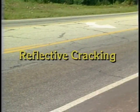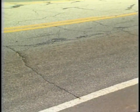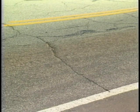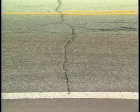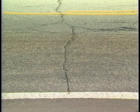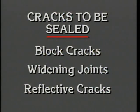Reflective cracking also requires crack sealing. This cracking occurs where Portland cement concrete pavement has been overlaid with asphalt. Usually, the joints and cracks in the concrete pavement will reflect to the surface. These cracks should be sealed to prevent water and incompressible material from entering them. Crack sealing is an effective maintenance activity for all of these types of cracks.